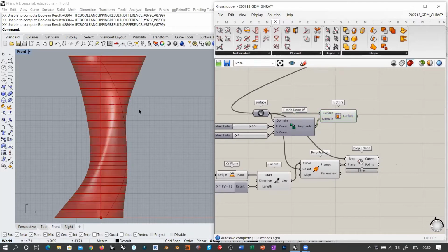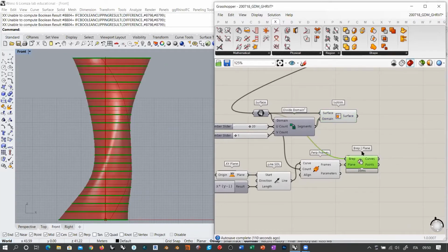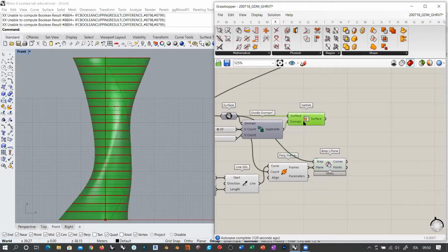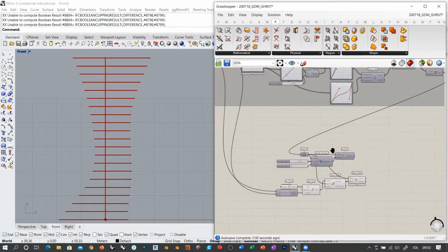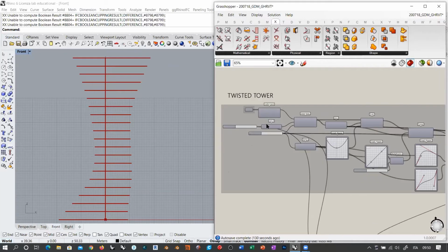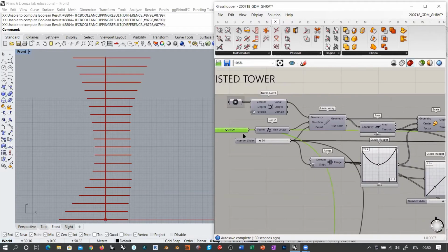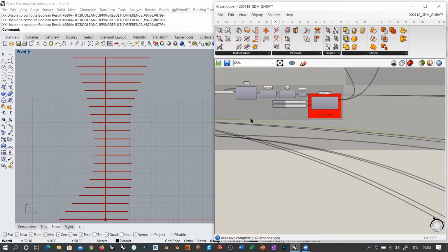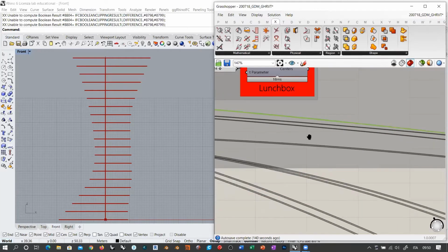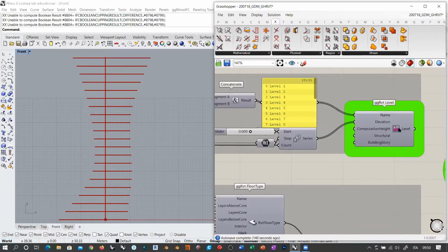Okay. You might also use this method that I am using here in order to create the first division. So for example, if you want to have at least a control over the horizontal divisions along the surface in order to be perfectly coincident with the actual floors, because remember that this thing here, you see this greenish wire that flows all through the definition, is going to define Revit levels.